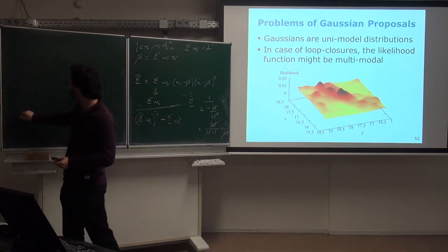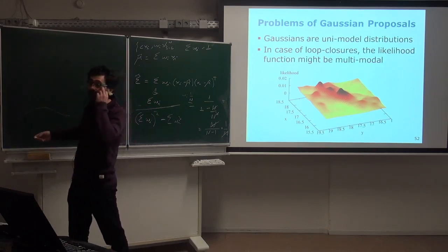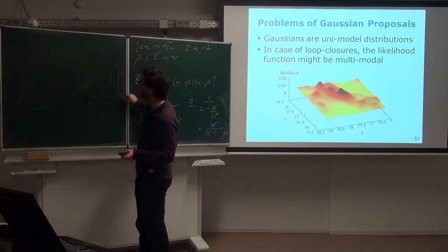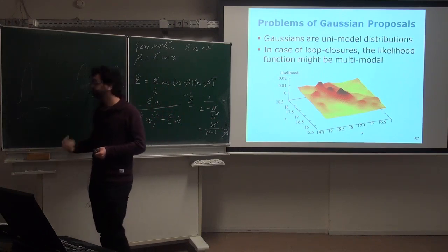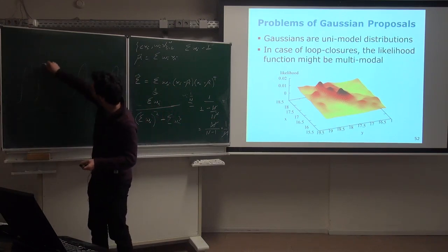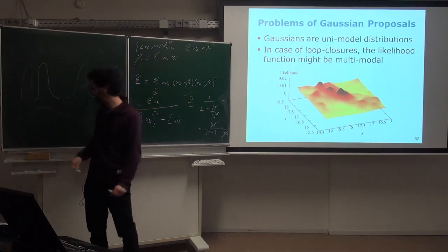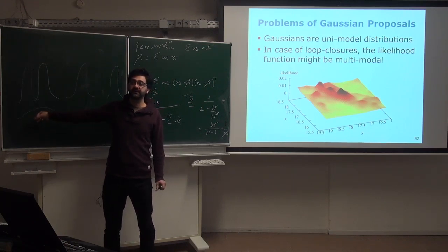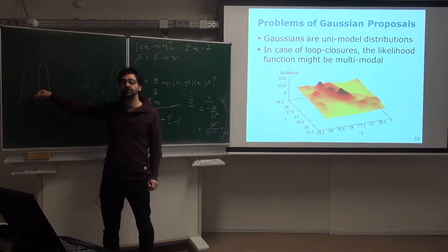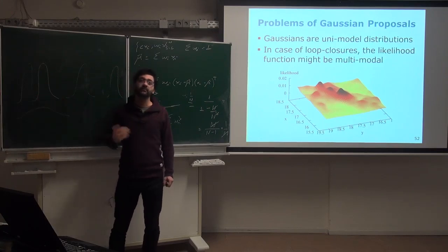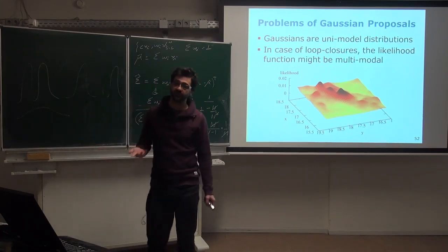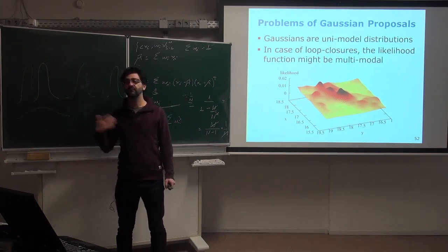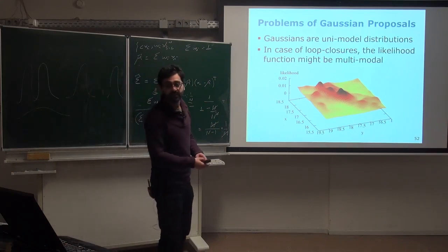So we often have, let's say, an odometry like this, and if you look at the likelihood, we'll probably have something here, and then maybe we have something here and something here, okay? But sometimes what happens is that we actually have multiple of these that can intersect the odometry. And if that's the case, then we might fail just because we are neglecting part of our distribution. So to say in different words, the Gaussian approximation that we do is too crude, too rough, and it's not a valid assumption or a valid approximation any longer, okay?